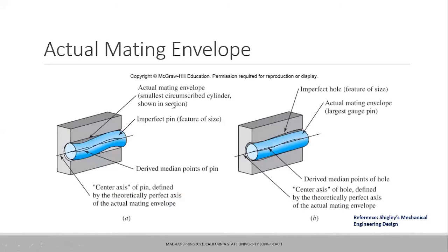For cylindrical objects, the datum feature simulator is basically a slotted bracket or a plate which has a perfect, precisely controlled cylindrical form, called the smallest circumscribed cylinder, shown in this section.